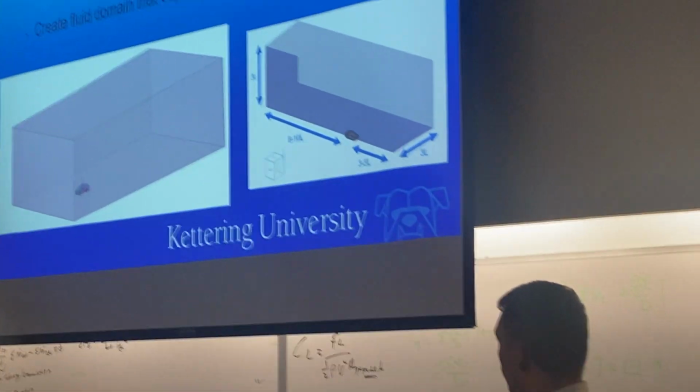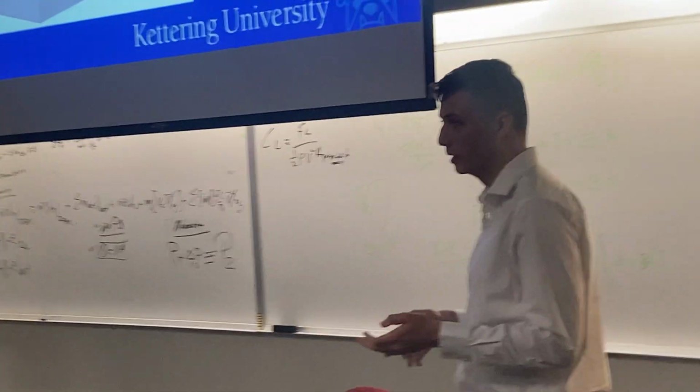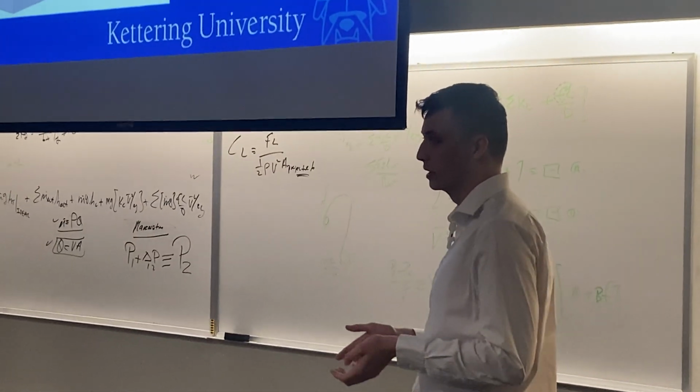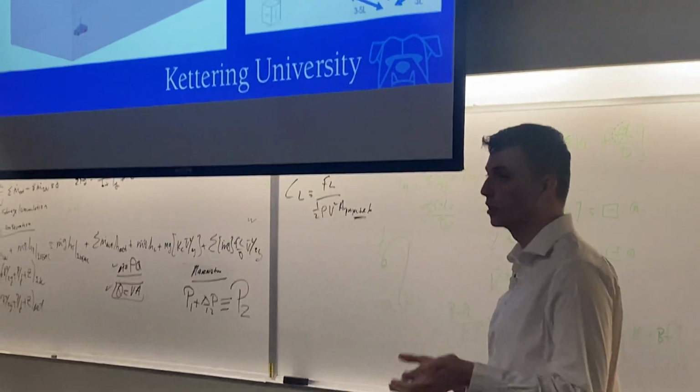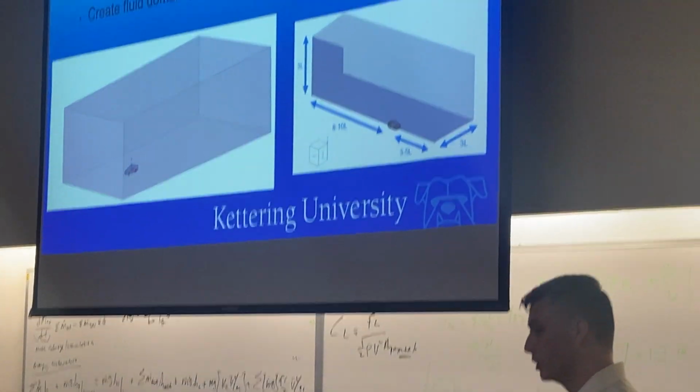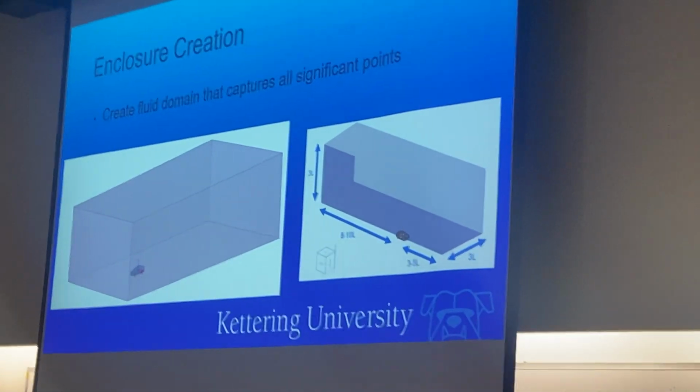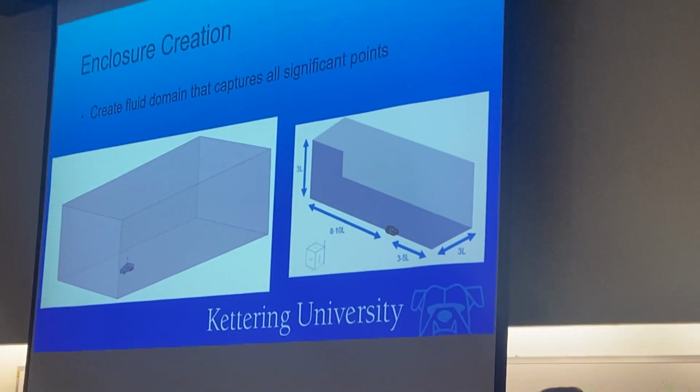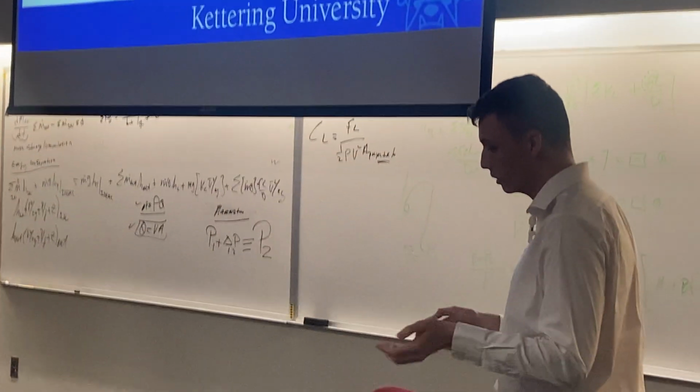So this is a static simulation. It's not a dynamic mesh, for example, like you would do a wind turbine to show rotation. This is just a static body that is subtracted from the fluid domain.